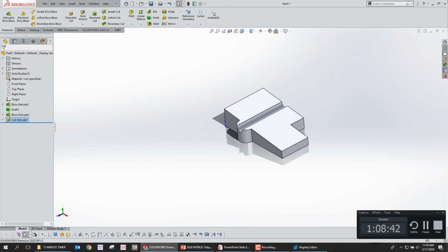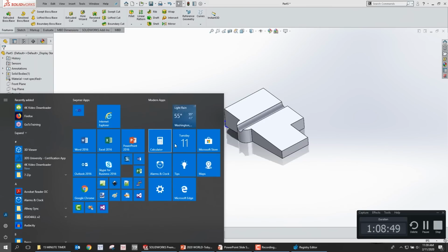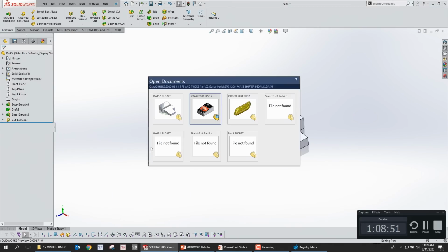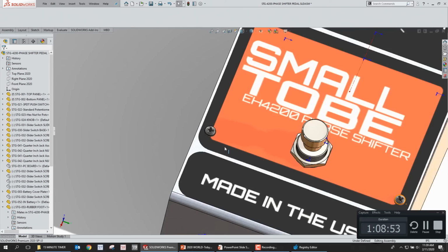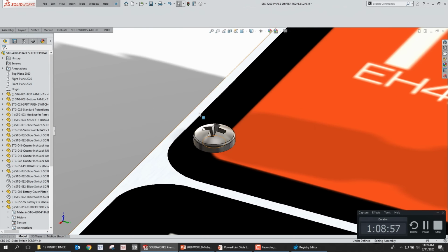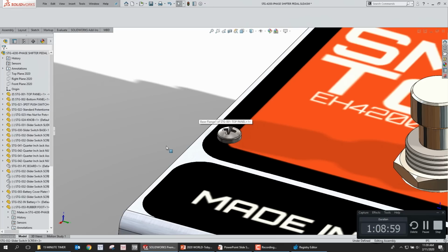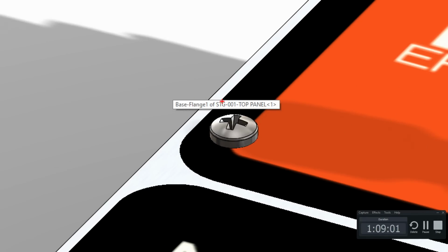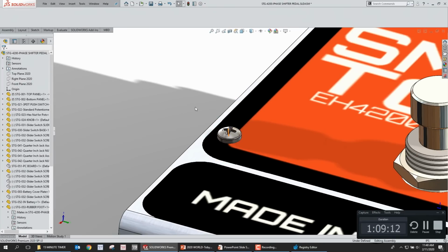Yeah, so this question is going back to the copy with mates command. It's a great question. So yeah, what happens is they get stacked in that case. The question was, when you have multiple components stacked on top of one another, how does copy with mates work? If you consider the screw and the washer as an internal system with mates between them, it'll always keep those mates between them and it won't ask you anything about them. It'll just carry it right with. So yes, absolutely it works. That's the short answer. It definitely works.